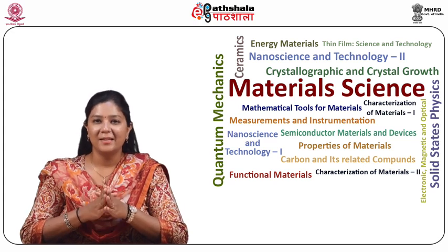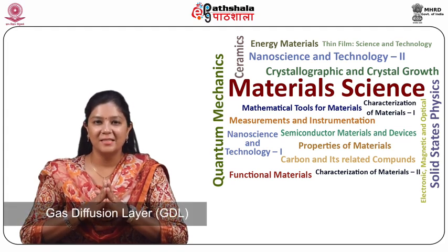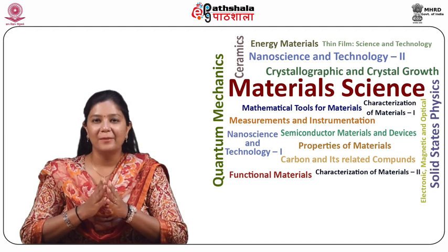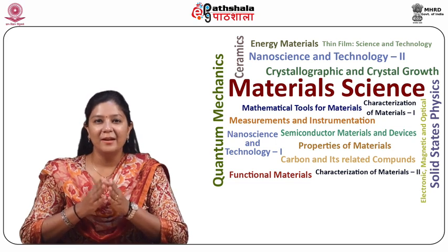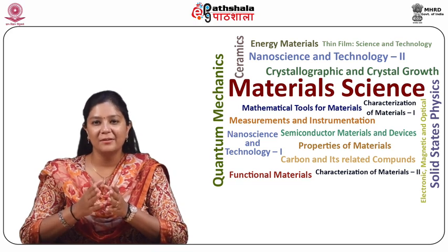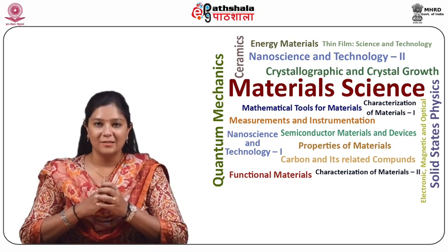Water and thermal management issues should be handled with great care with new types of gas diffusion layer, GDL, for example carbon cloth or metal, for better electron transfer and mass transport of the reactants and products. A well-defined fluid flow path in the GDL and electron transfer through a solid metallic structure would reduce overpotential losses.